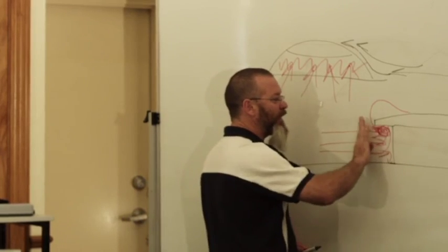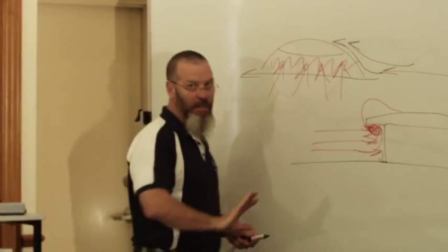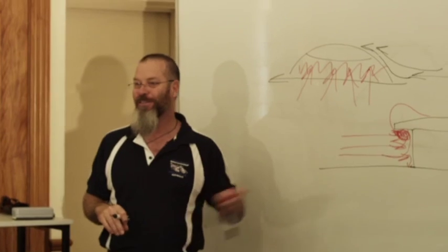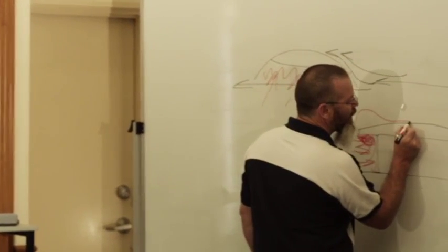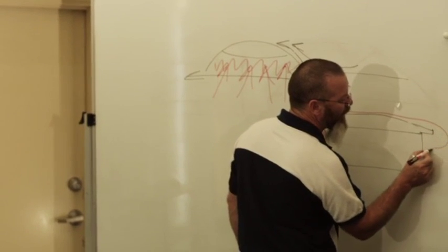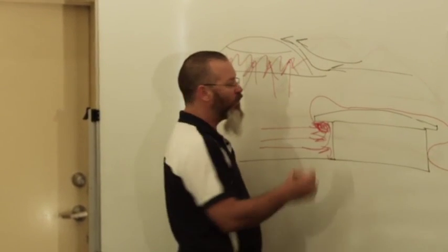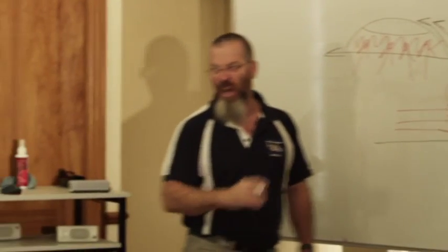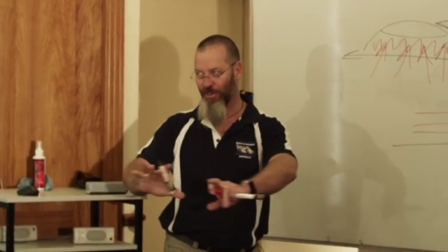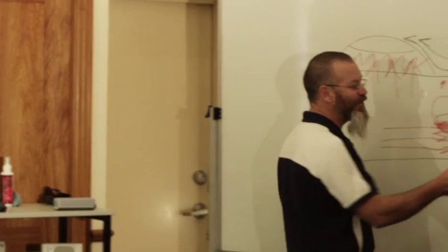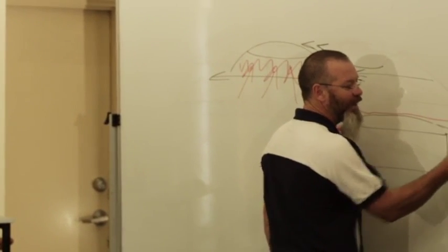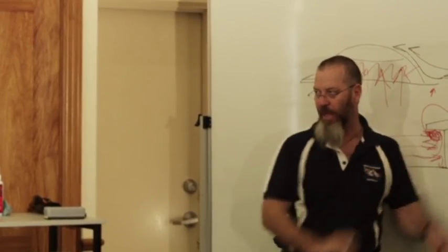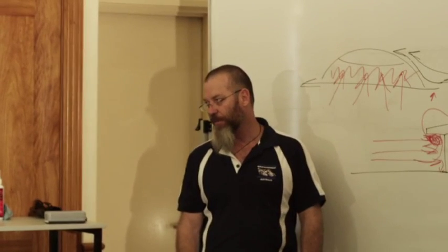Again, as I said, the wind doesn't come out and go just 90 degrees and back across. Because of this viscosity, it forms this, and I use the term loosely, Bernoulli bubble at the outer edge here. Then it comes across here and it does the same again, creates a Bernoulli bubble at the side of the building. So what you're getting here is an uplift at that point, an uplift Bernoulli bubble. And again, don't try and Google my words, I'm just trying to keep it simple for us builders. And here you're getting what we call a racking bubble. So this one's more focused on bracing, trying to pull the building over or rack the building. This one here is more focused on uplift.